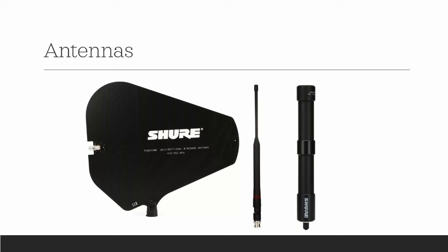The nulls from your multipath, which I talked about in terms of antenna placement and the surfaces around it, are minus 30. So multipath reflections can create bigger headaches for you than polarity. With all of that being said, there are antennas, helical antennas for example, that are not polarized. So if you've got a performer who's moving around a lot and orientation may be a concern, that is a better option for you. There's always options to work with.